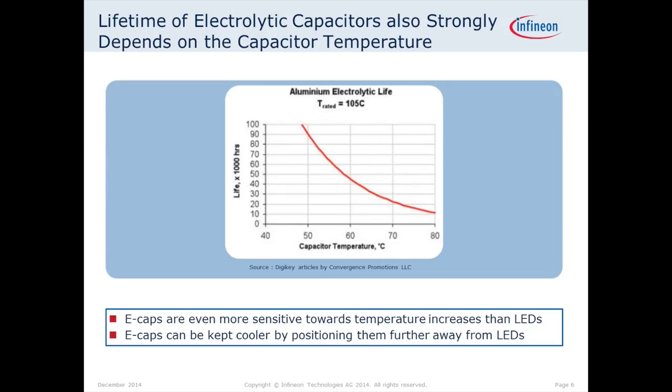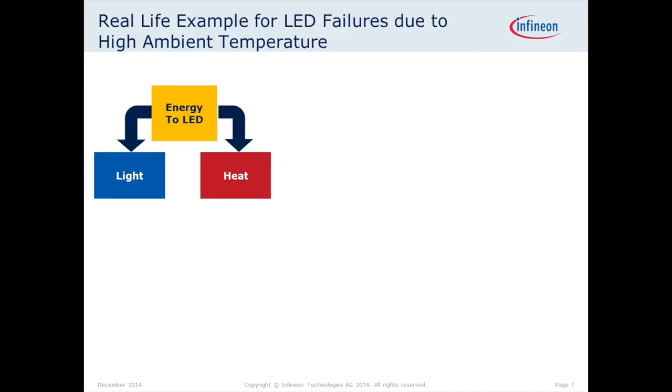So in other words, it's also the end of life of LEDs. As most of you know, it's not a sudden death, but light output, lumen output goes down gradually. So in other words, the electrolytic caps are very often the lifetime-limiting factor, as the LEDs in some cases as well. Now, why are we talking about heat so much?